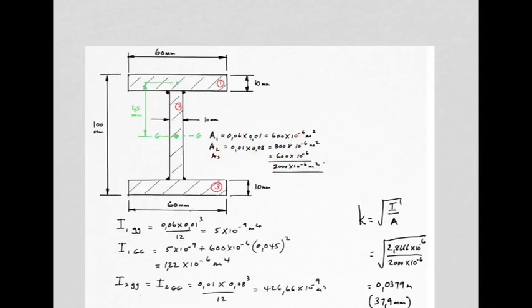Normally at this point we would then use the areas to find the position of the centroid, but as I said earlier, the centroid of this symmetrical shape will indeed be at the midpoint over here. So we're not going to need the areas for that purpose, but we are going to need the areas later on, as you'll see when we use the parallel axis theorem.